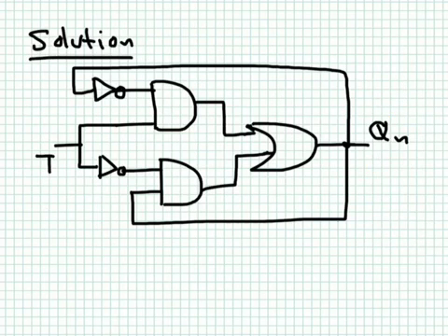So this one is a possible implementation. If you have 1 here, this will toggle the output. If the output is 0, it changes to 1. If the output is 1, it changes to 0. Of course, I cannot have 1 here for long, because if I have 1 here for long, this will toggle the output, resulting in feedback to the input, which will result in more toggling. So remember, this input here will have to be very limited in time, and this can be edge triggered.